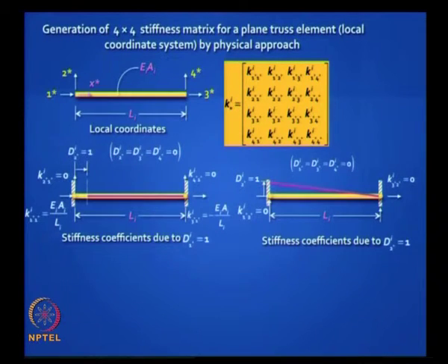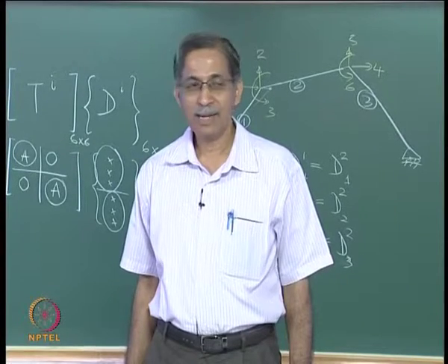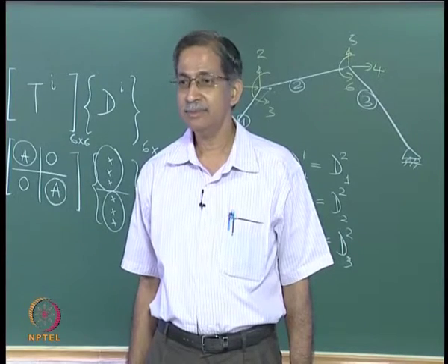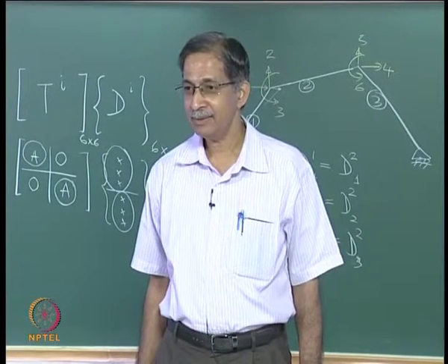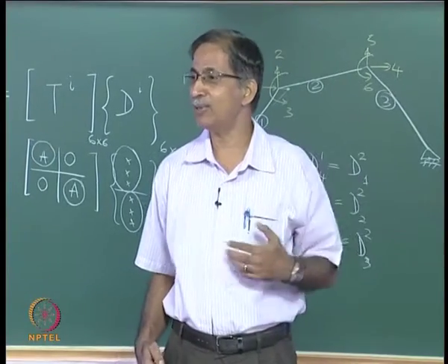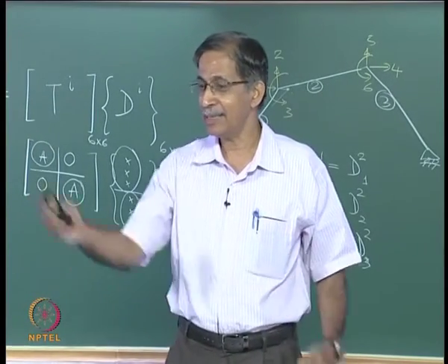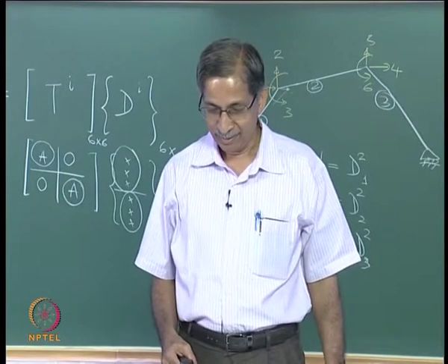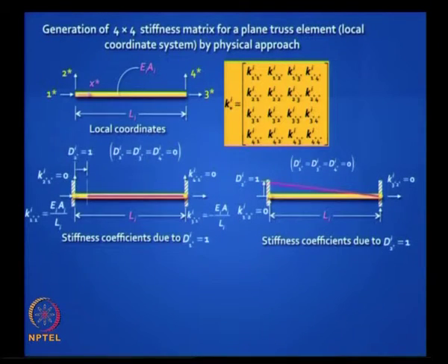You see, all you have to do is to lift it up. Yes, sir, like a rigid body. Then what? But why not displace it? That member has stiffness only along its own axis. So he gave the correct answer. All you do is to lift it up. It will move like a rigid body because you are allowing that movement, and it's pin jointed.